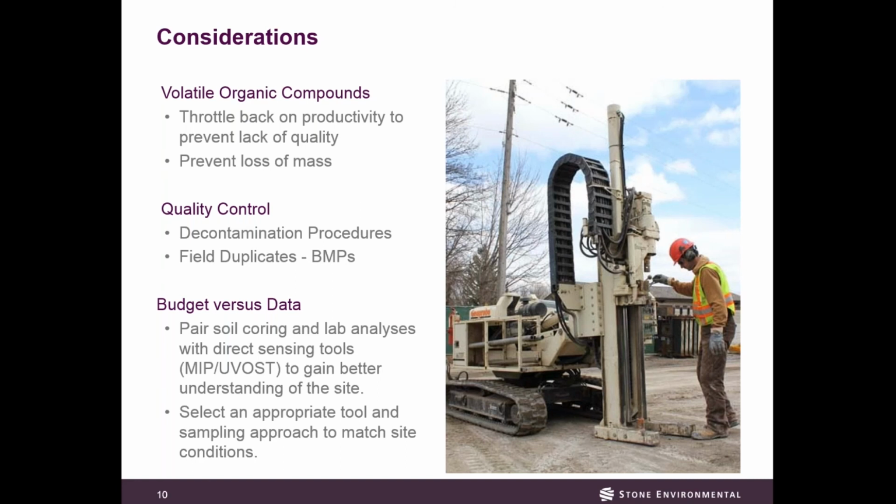If you have gravel, you're not going to go at it with this because you won't get any sample in your core. This is 9/16 of an inch outer diameter of the sleeve. You're just not going to do it. You're not going to get any sample. So you've got to go wider. You've got to come up with another way to go about it.